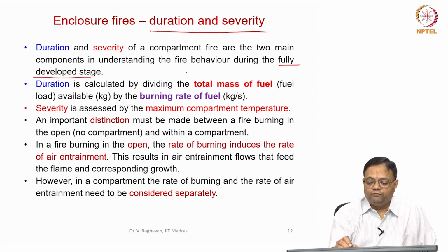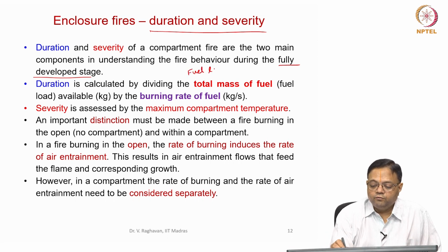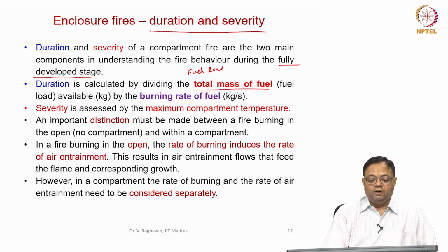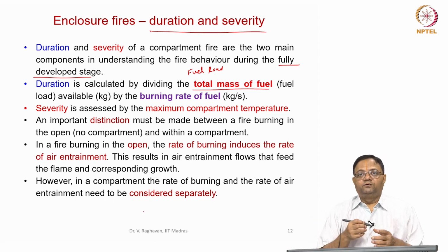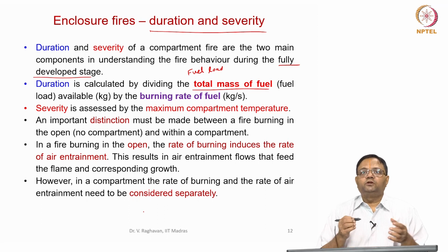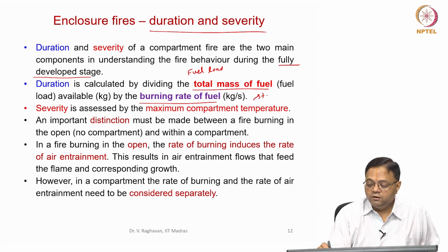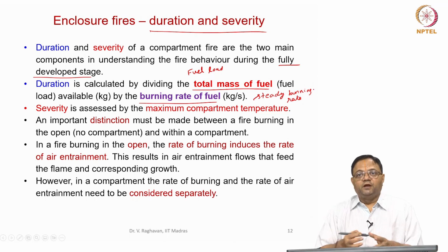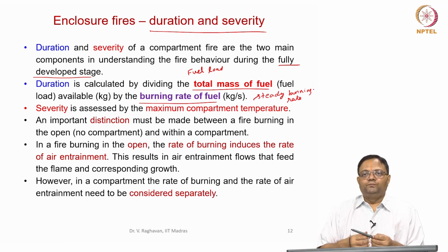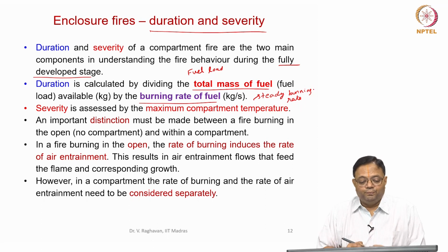So, as I told you, you first need the fuel load, that is the total mass of fuel available for burning, and there are several commodities. Each commodity can burn with its own burning rate. When you say burning rate of the fuel, it is the steady burning rate. Once the flame is formed over the material, it consumes the material. That is the burning rate we are talking about here.